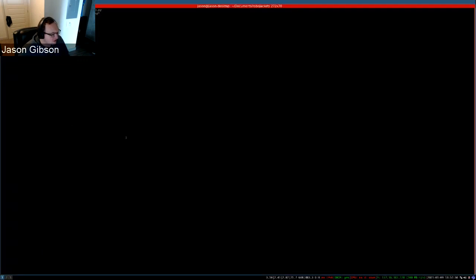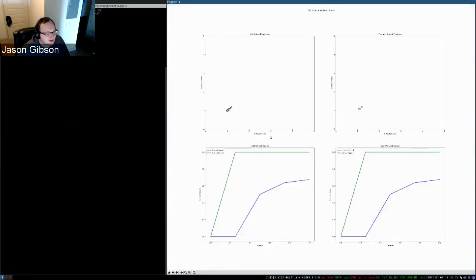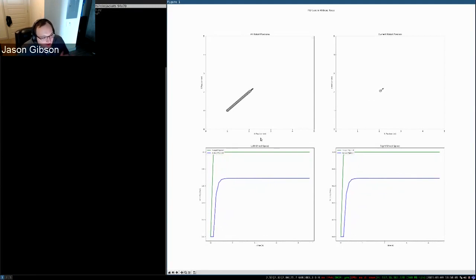And now we're going to rerun this simulation. We're going to skip the first one, and this is just going to be PID without noise. So you know how I saw before, we were sitting around 0.4. Now we're sitting around 0.7-ish. So we increase P to the point where it's good.